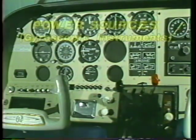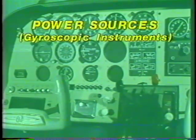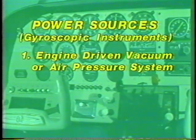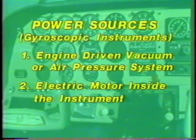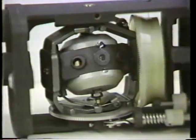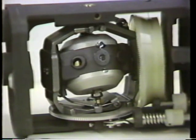There are two commonly used power sources for gyroscopic instruments. The engine-driven vacuum, or air pressure system, is used because it is a simple, reliable system and is usually the power source for two of the three gyro instruments. The third gyro is usually powered by a small electric motor inside the instrument. The vacuum, or pressure system, spins the gyro by drawing a stream of air against the rotor vanes to spin the rotor at high speeds. This is essentially the way a water wheel or turbine operates.